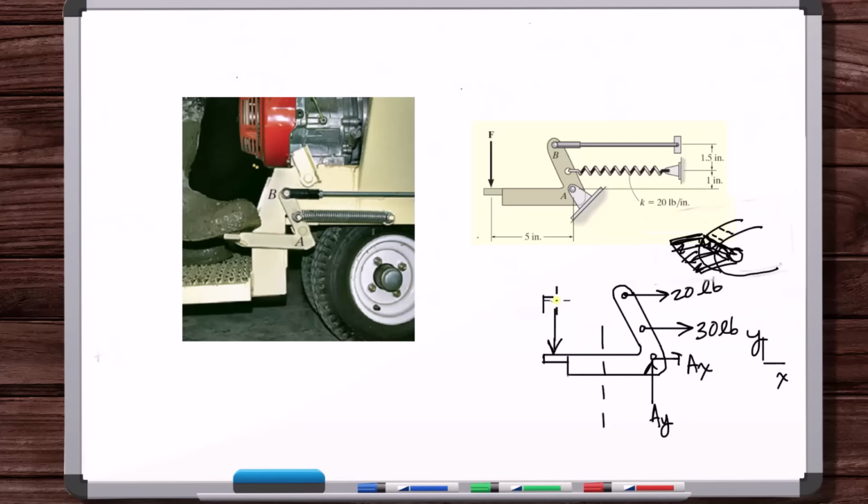A cut here and removed all of this. Is the size of the area negligible? No, it's not negligible, because if you could put the resultant force here, you could maybe put it here or here. I mean, it is pretty small, but it's like saying, well, then I could put this 30-pound force here or here. Well, no, you can't. You need to know where it's at.